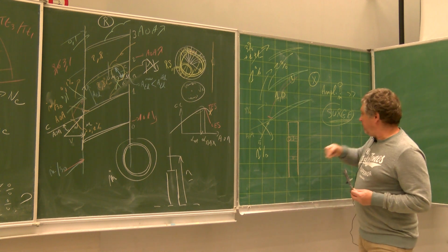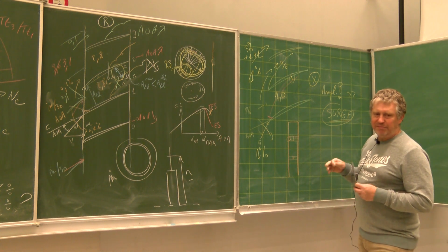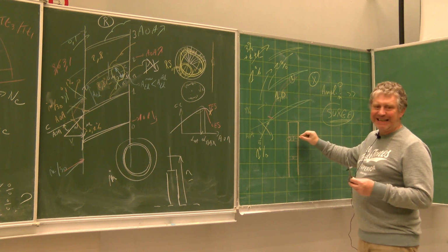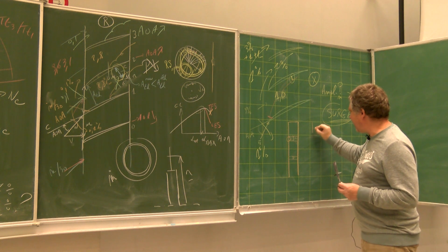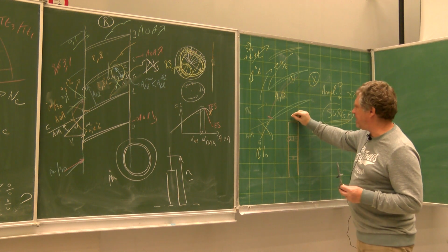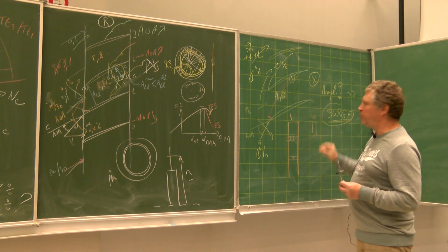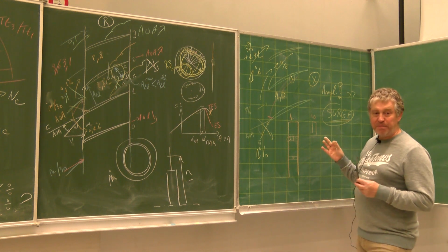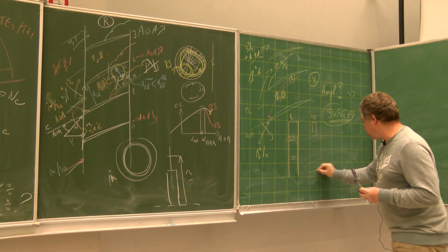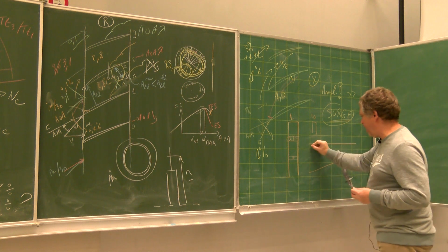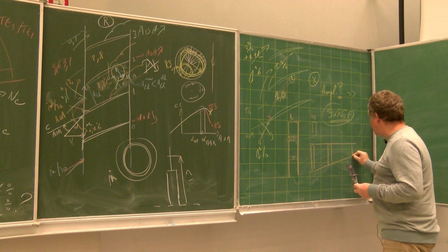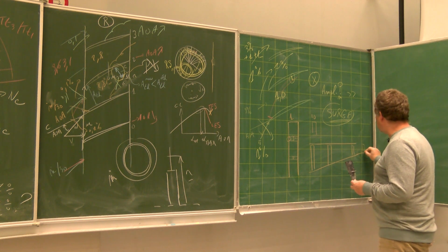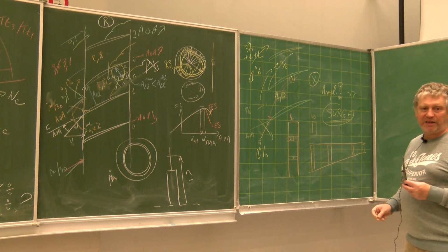And so if you have a certain height, a certain delta R that is impacted here, and if you go to the last stage, so this is, let's say, stage 1, and you go to the 10th stage, the 10th stage is much smaller blade because the compressor is built like this with a compressor blade that is here, and the compressor blade is becoming smaller and smaller, and if you continue, you have a very short blade at the tip.